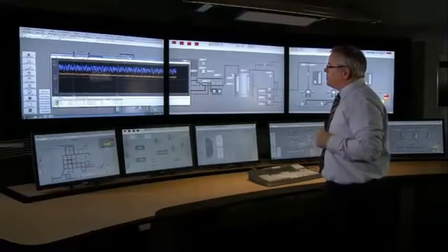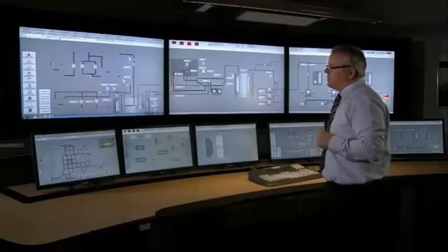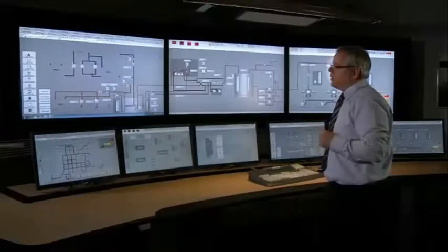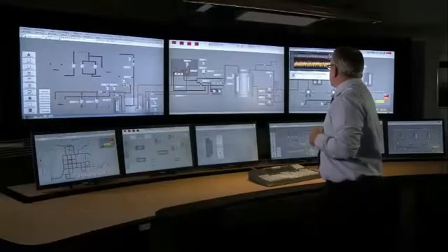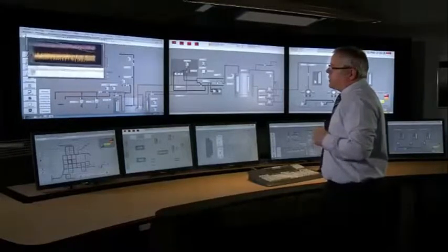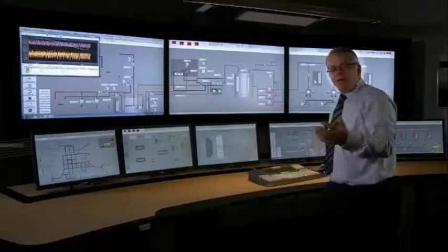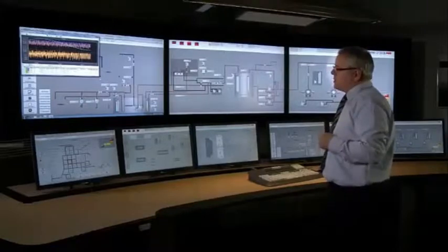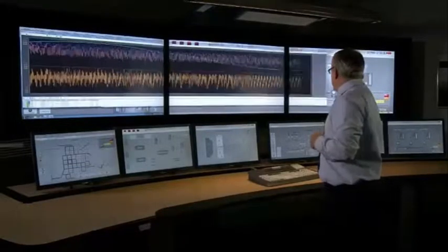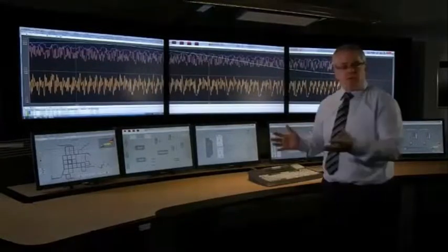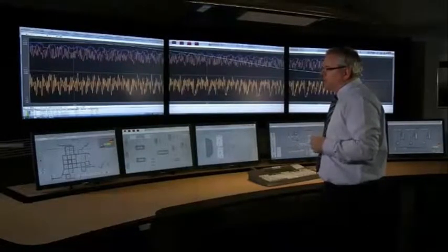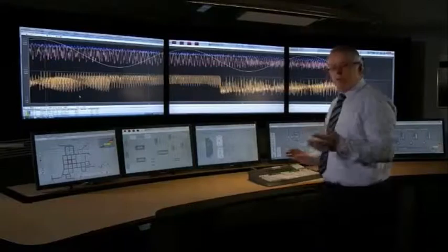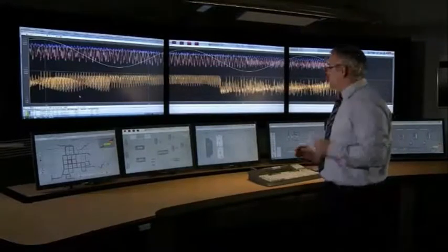Likewise, we can have pre-configured reports for traces that are useful on a more regular basis. And this is an area trend. By selecting this, again, we can drag across the workspace and utilize the full area of the workspace simply by dragging the box all the way across. And there's the full trend data. This is historical data based on the length of the logging period. On this demonstration system, we're logging for 4 hours. It could be 4 months, it could be 4 years.